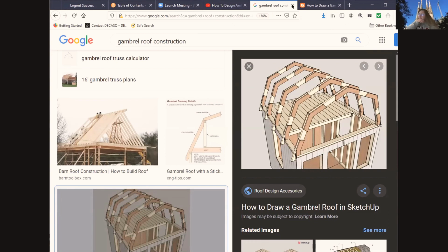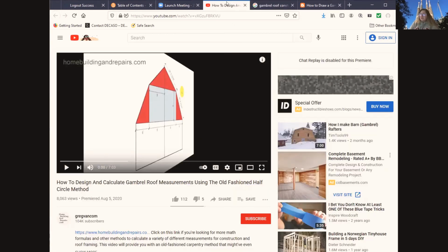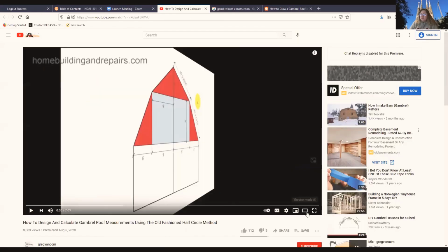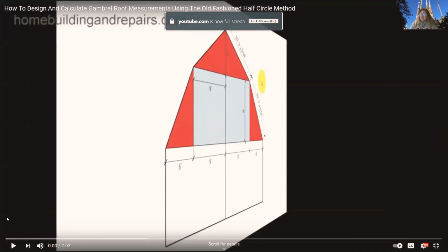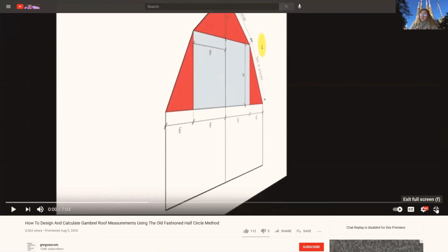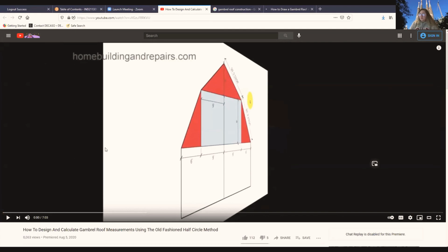And it's made of rafters that are made from 4 sections of plywood, and gussets are attached to the joints. And you construct the entire piece first, and then you attach it to the walls. And then you cover the roof with plywood. The pros are it provides the advantages of a sloped roof while maximizing headroom inside the building's upper level. And the cons are just that it's more expensive because it requires a lot of materials, and it's time consuming to assemble. It's a lot of pieces.